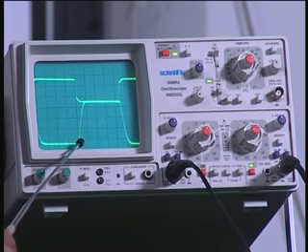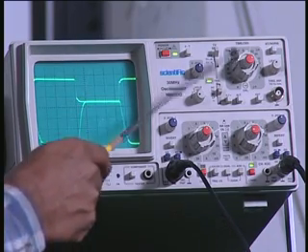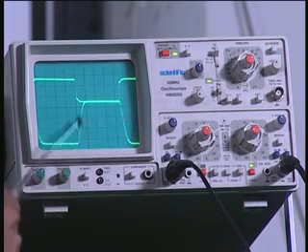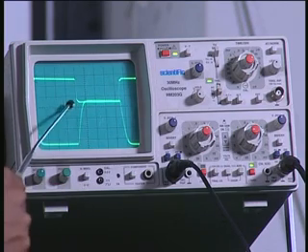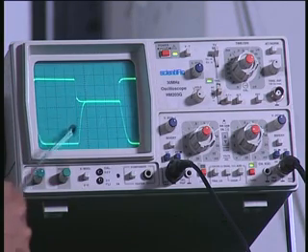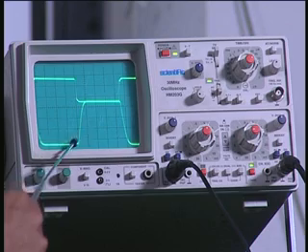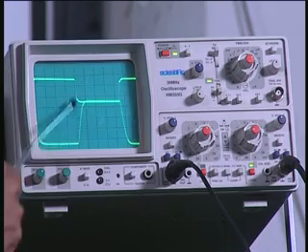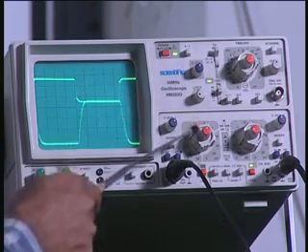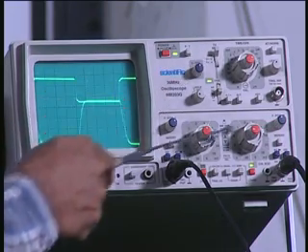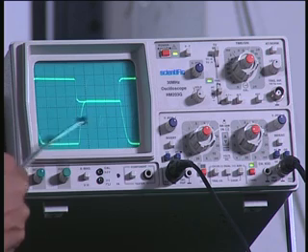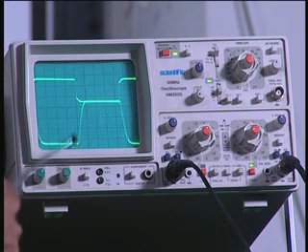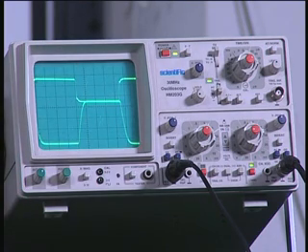Now if I calculate what is the gap here from the microsecond that I can read from here, and from the amplifier gain factor, I can find out what is the amplitude here. Divide the amplitude by this delta t, which is read from the oscilloscope, you can get the slew rate, and in this case if you actually take a close look at this, you would find it comes to around 2 volt per microsecond. So this corresponds to the slew rate of the operational amplifier.